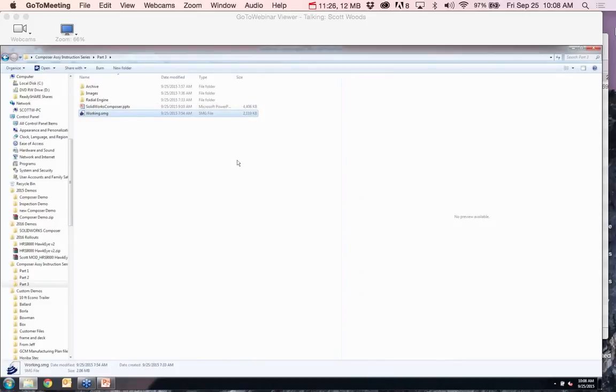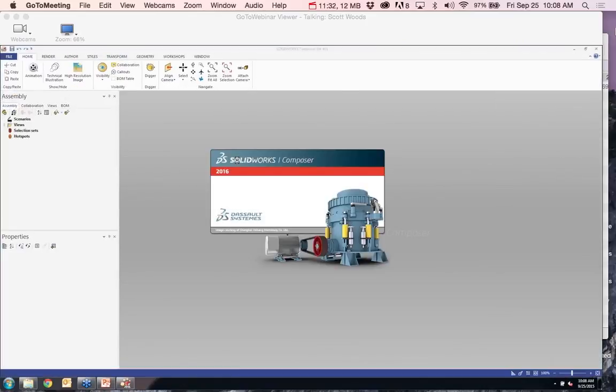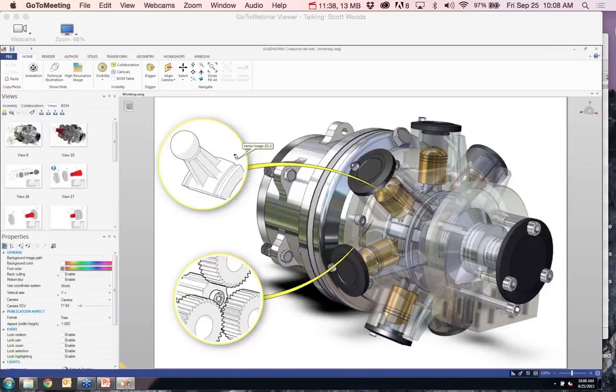If I click on it, I'm going to load all the content that we did over the last 2 Fridays, and it's just a matter of a couple seconds. So with that said, it is loaded now and has everything to do with this model, and it's a 2 meg file. What we're seeing typically is about a 40 to 1 ratio, and so this assembly in SOLIDWORKS is about an 80 meg file.